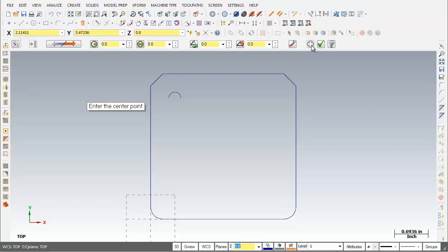Now on to arc number 2. Now as you can see on the screen, we're prompted to enter the center point, so let's get that sorted out. So I'm going to move on up, click in the X box here, and then what I'm going to do is put in 0.5, hit the tab button, and we're transported over to the Y, and for the Y 0.5, going to hit the tab button and the tab button once again. So we're prompted to sketch the initial angle.